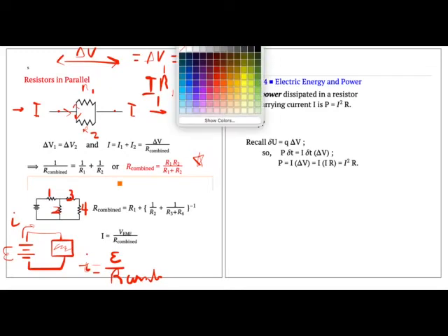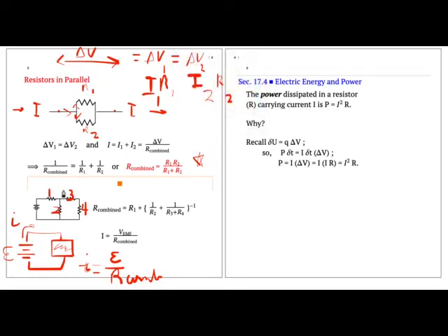So let me annotate this with a different color. Take these 3 together. Those are in series with I1, because any current that comes into I1 also goes through this network of 2, 3, and 4, comes out the other side.